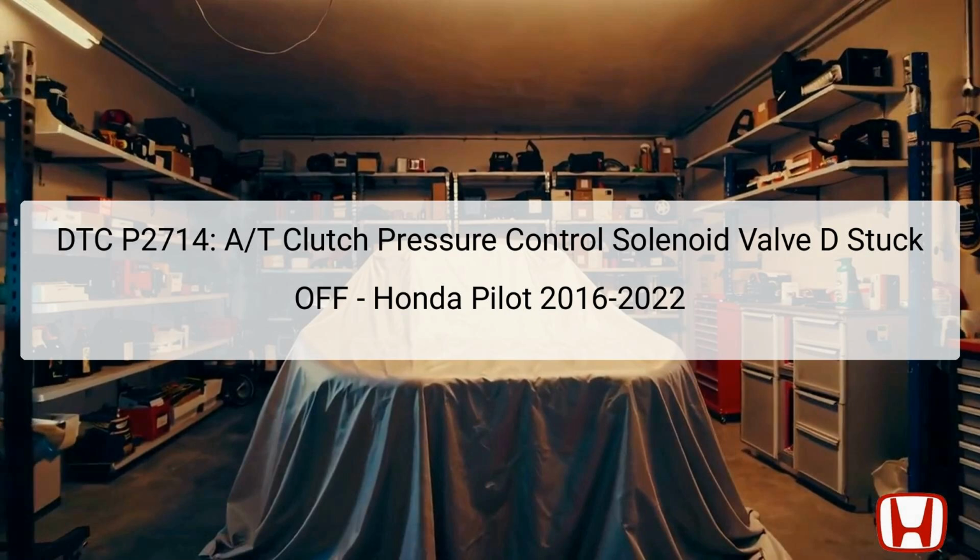When diagnosing the P2714 code, it is crucial to ensure that the automatic transmission fluid is at the correct level and free from contamination, as this can impact the solenoid's functionality. Proper diagnosis involves checking for metal debris or excessive clutch material, which can indicate internal transmission damage. Each of these components and steps plays a significant role in ensuring that your Honda Pilot operates smoothly and efficiently.